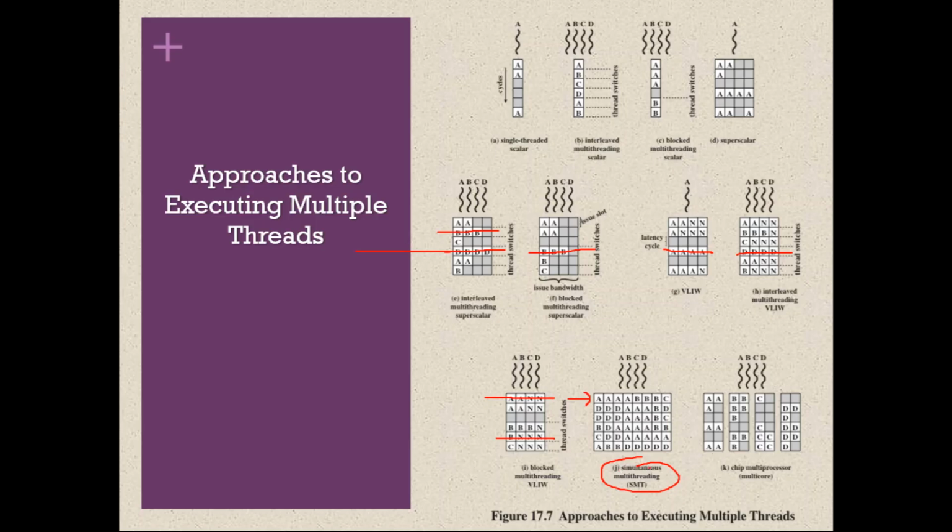Here we are considering simultaneous multi-threading with 8 issues that can be given parallelly. It means we have 8 execution units. These are the available threads A, B, C and D. The processor will first try to fetch 8 independent instructions from thread A, but it got only 4 independent instructions.